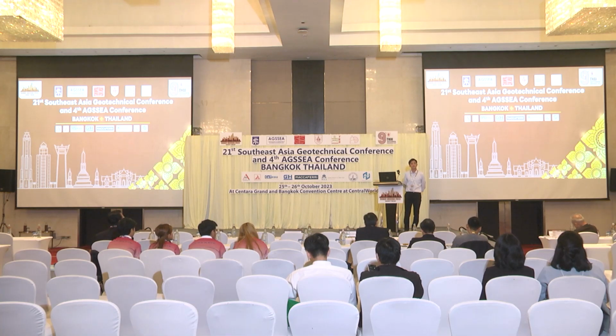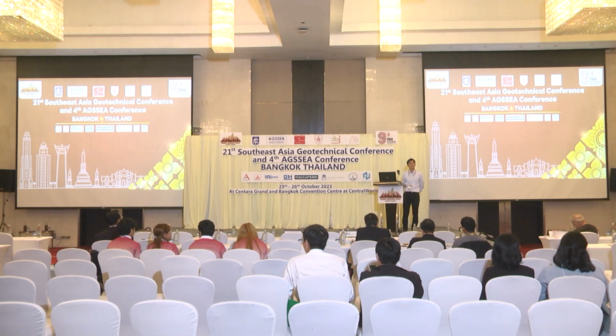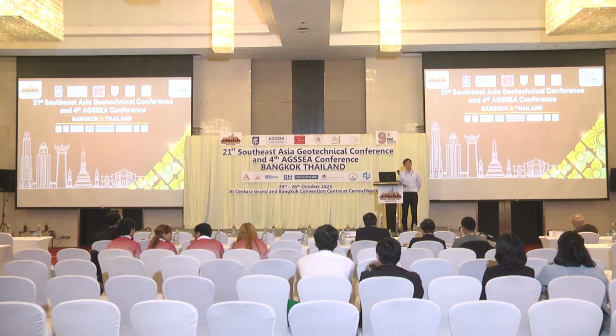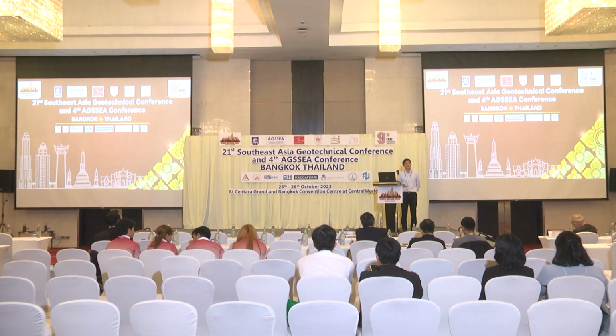If you look at it from an unsaturated soil mechanics point of view, maybe you can find a nice explanation about how this layered soil cover system works, like characterizing it in terms of a K function, soil water retention curve, or something like that.